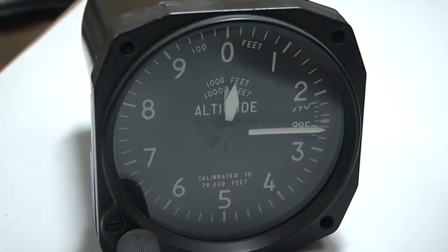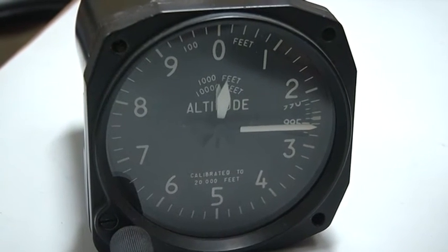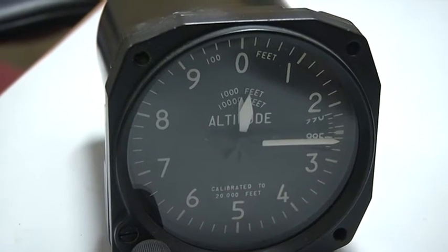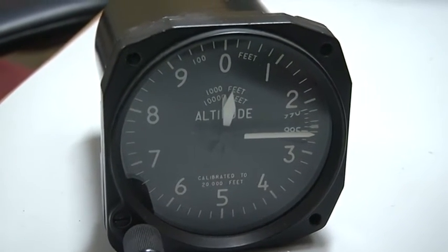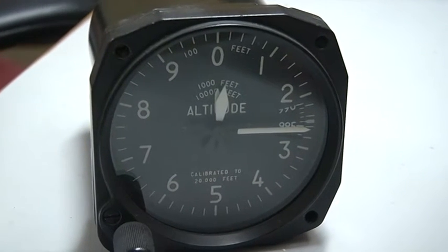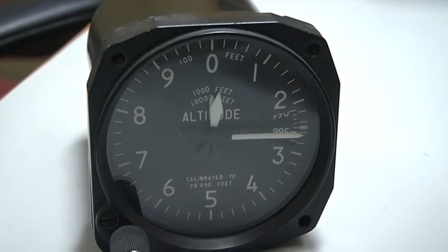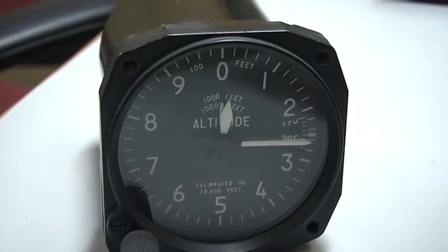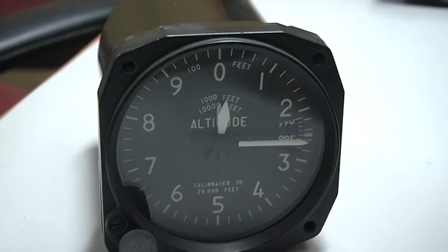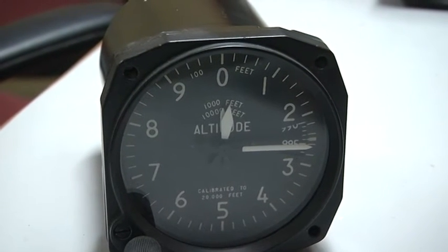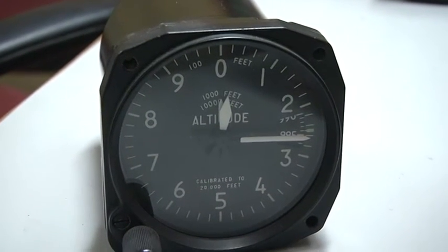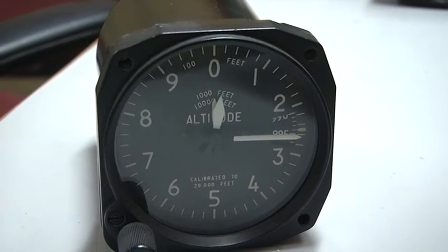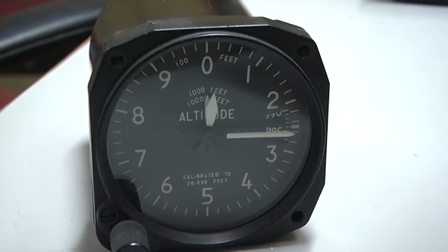Three needles can be seen on the gauge. The smallest one, the intermediate, and the longest one are there for indicating the altitude in different thousands of feet. The smallest needle gives the reading in tens of thousands of feet. The intermediate one gives the reading in thousands of feet, whereas the longest needle gives the reading in hundreds of feet. And the Kollsman window is used to set the barometric pressure by the knob, so that the pressure can be related to the atmospheric pressure when the aircraft is flying.